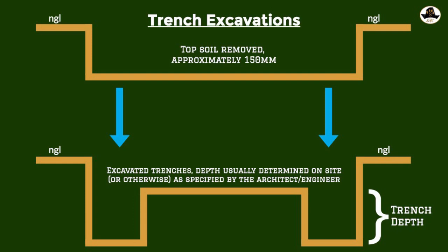Usually, according to engineering calculations, the normal standard is for the building to have stability, you have to have 45 degrees on either edge of the trench, and that is also determined when you ensure that the trench width is triple the width of the wall that is going to be constructed in that trench. Yes, so that's how you ensure that you have that 45 degrees. It's basically an engineering standard that has been set, so just follow that and ensure that our buildings are stable.